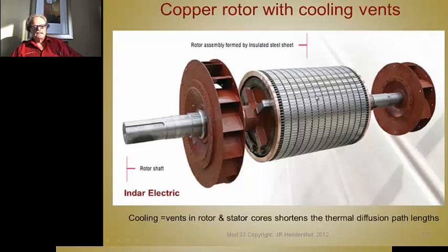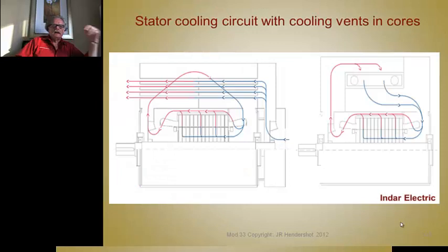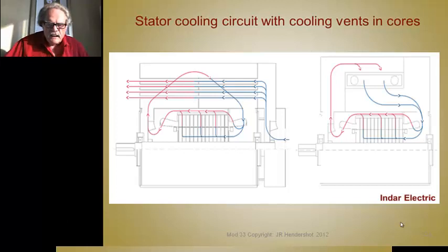certainly these cooling vents in the stator and rotor core shorten the thermal diffusion paths. That's their purpose. And here are some of the circuits that you see that are generated from these paths. Here's your stator, and there's your rotor, and the ventilation passageways are lined up between the rotor and the stator.